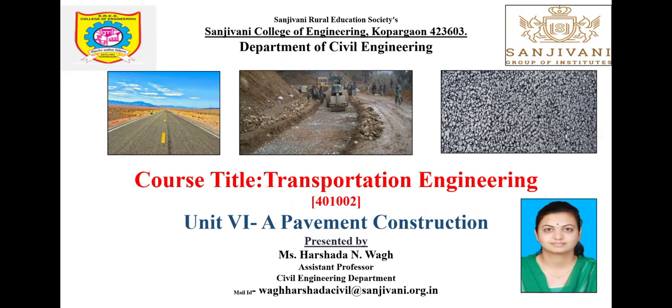So, why should it be provided? What is the purpose of providing the road pavement? It will help us to carry the wheel load or whatever traffic is going to move. Secondly, it will help to distribute the vehicular load over a large area of the underlying subgrade soil. Also, it will provide a smooth surface for the to and fro movement of the vehicles, and it will prevent ill effects of weathering actions on the subgrade soil. So for all these purposes we have to provide a proper road pavement.